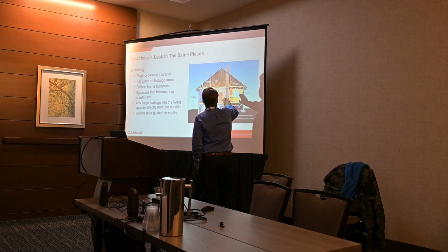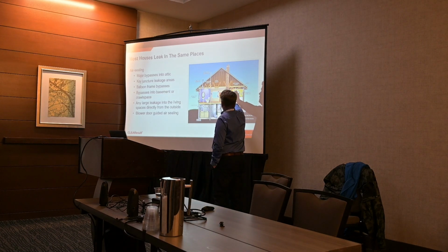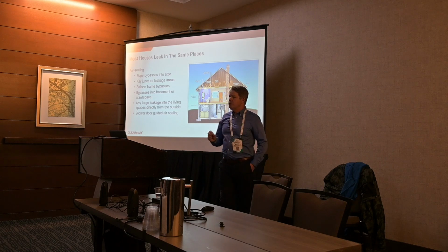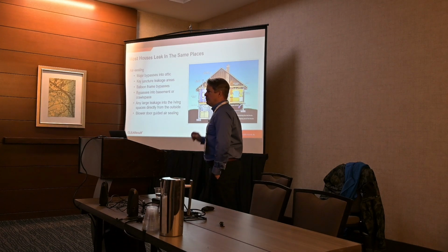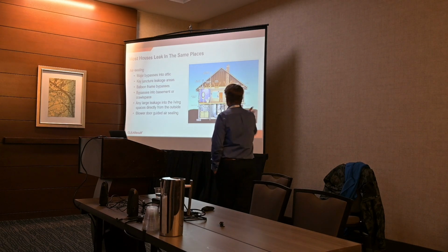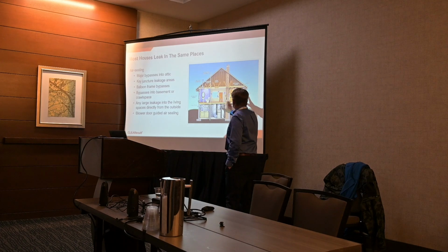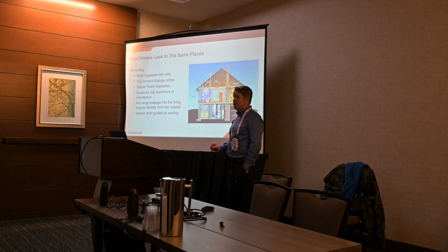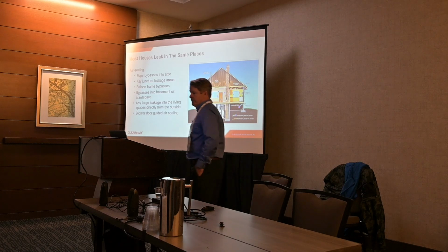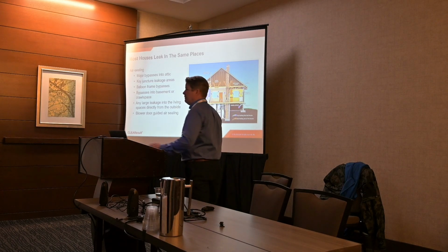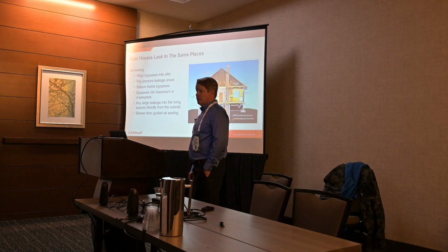You can, if you want the homeowner to be able to see it, rather than depressurize the house, pressurize it and then use smoke, and the smoke will go right to the hole and go right through it. It's much easier to find leaks when you pressurize the house with smoke. If you depressurize it, it just kind of blows at you, but when you pressurize it, the smoke will go right to the hole. You can see it much more easily, and the homeowner can see it too. But typically the blower door is depressurized. Yes, you'd have to spin the fan around.